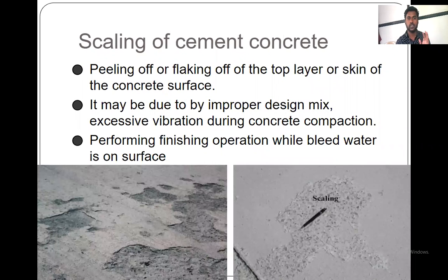You can see here scaling of the cement concrete, the cement paste that is there on the road surface may get removed out. The peeling or the flaking of the top layer of the skin of the concrete surface gets removed. Such type of failure is called scaling of the cement concrete. It may be due to the improper design mix or the excessive vibration in the building.